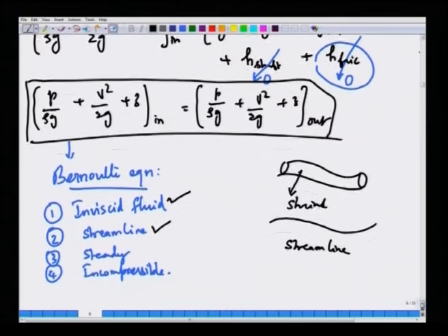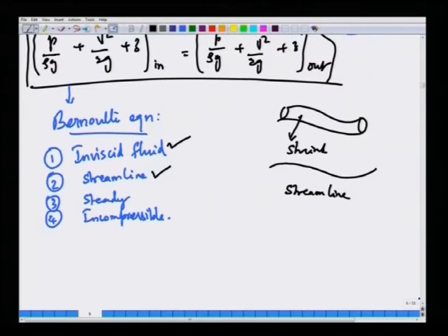Whereas, the energy balance that we wrote is generally applicable to any control volume, and as long as you can supply the problem with the information about what are the viscous losses, you can completely solve it. And it is applicable to any flow of viscous liquid into any equipment like a pump or a piping network and so on. As long as we know what are the losses, we can certainly solve that most general energy balance equation, the integral energy balance equation.